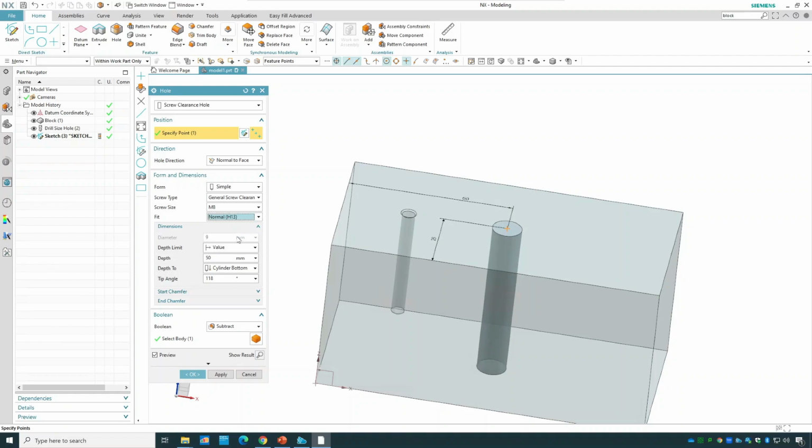If I go with the normal fitting, which basically is a 1mm gap and 1mm clearance. If I go with the loose, basically they're 2mm and that becomes loose. And of course, I would be able to customize it. I can go and put the exact 8mm, which is almost impossible because of course you should have some sort of clearance. The clearance is really important.